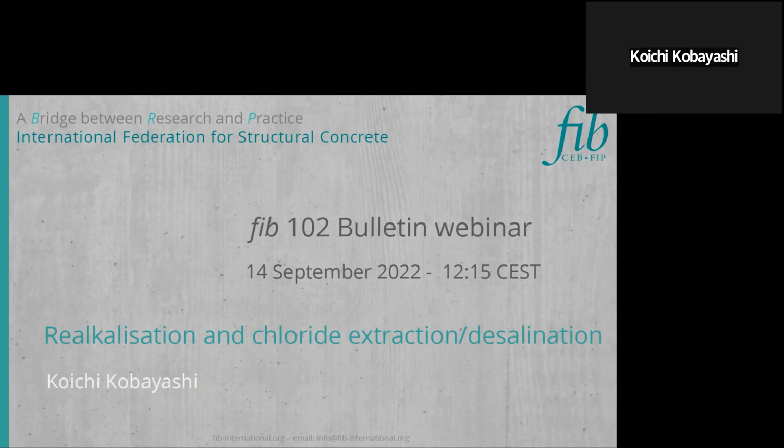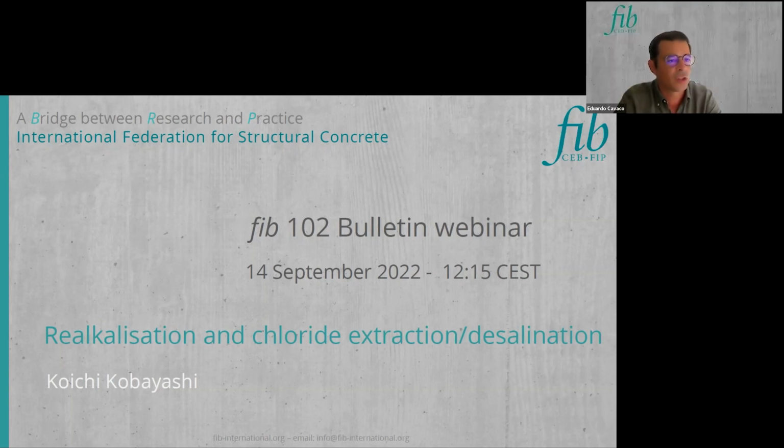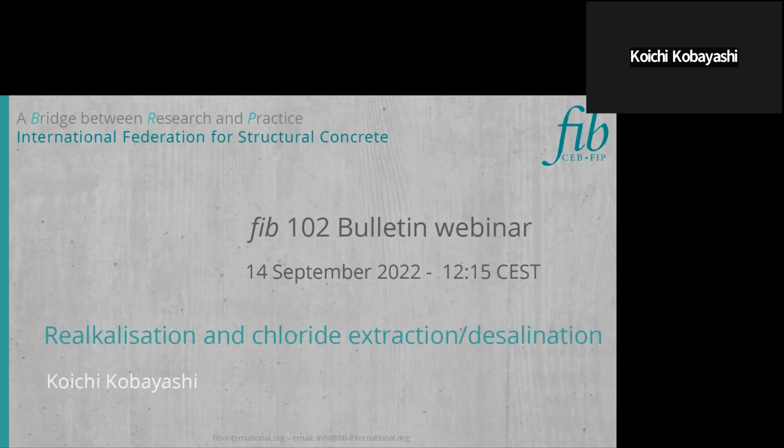You mean if much more voltage is applied, what happens? Yeah, if it is dangerous when applying. It may cause hydrogen enrichment of the rebar, and it generates hydrogen gas.